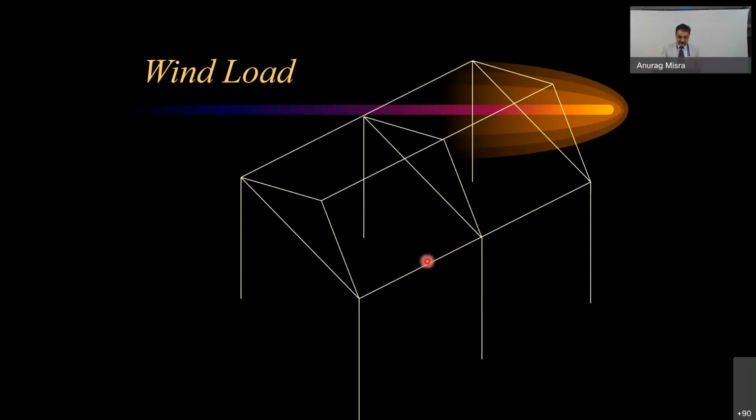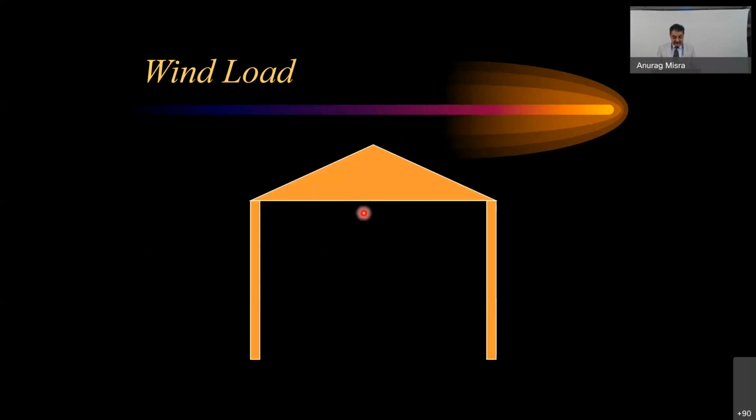Also, we have to consider certain other conditions, that if your structure is something like that, you calculate the wind pressure depending on the slope, etc. But if your structure is not in this shape, for example, if this is the case, if something is coming cantilever, right, and so the wind pressure drastically changes, because it's like a kind of railway platform kind of loading, and is creating quite substantial pressures as compared to the other kind of loading we are considering.